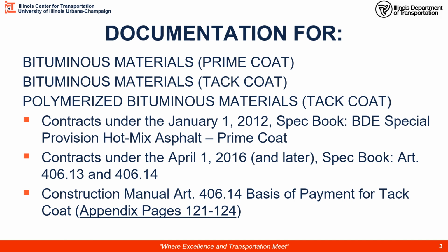So in the 2016 book, Articles 406.13 and 406.14 apply. If you want some more information, the construction manual also has some information under 406.14, the basis of payment for tack coat. Also, the appendixes, pages 117 to 120, have good information. Those are all good to tab for conducting work on bituminous materials, prime and tack coats.